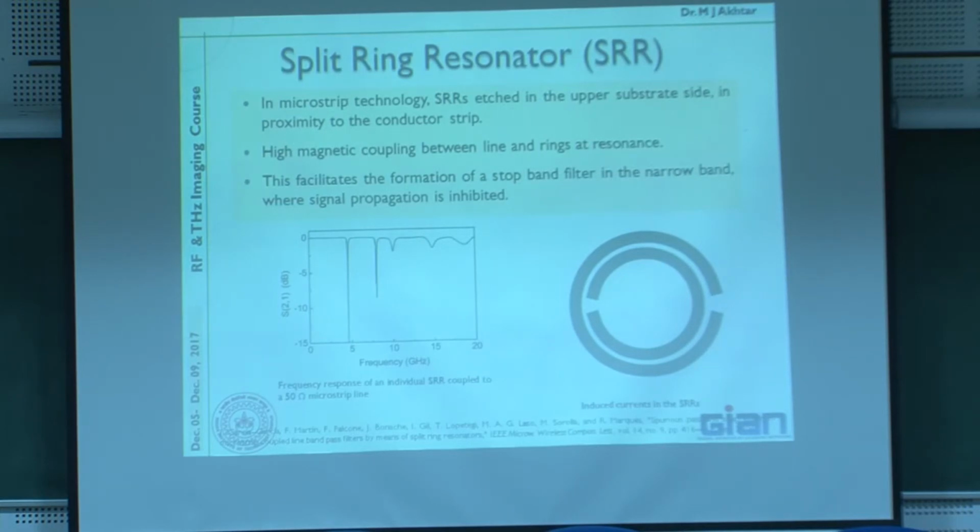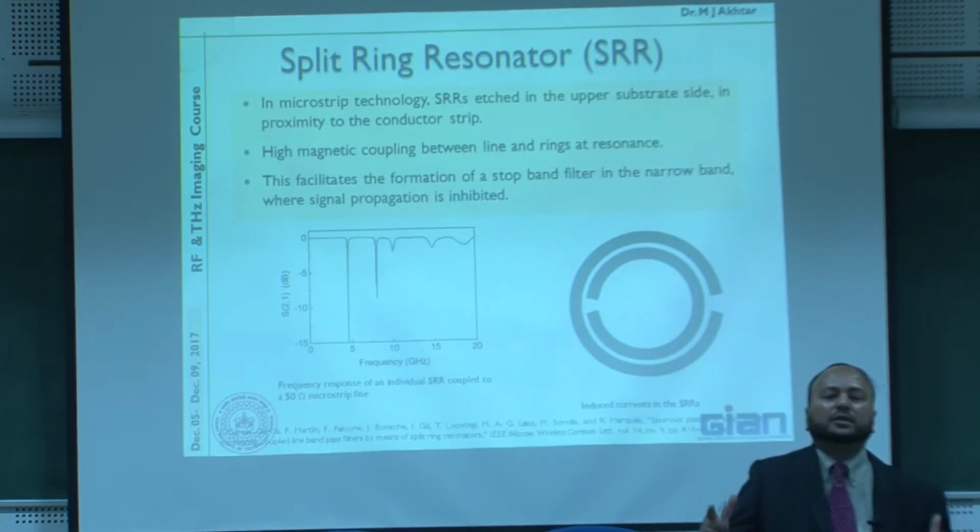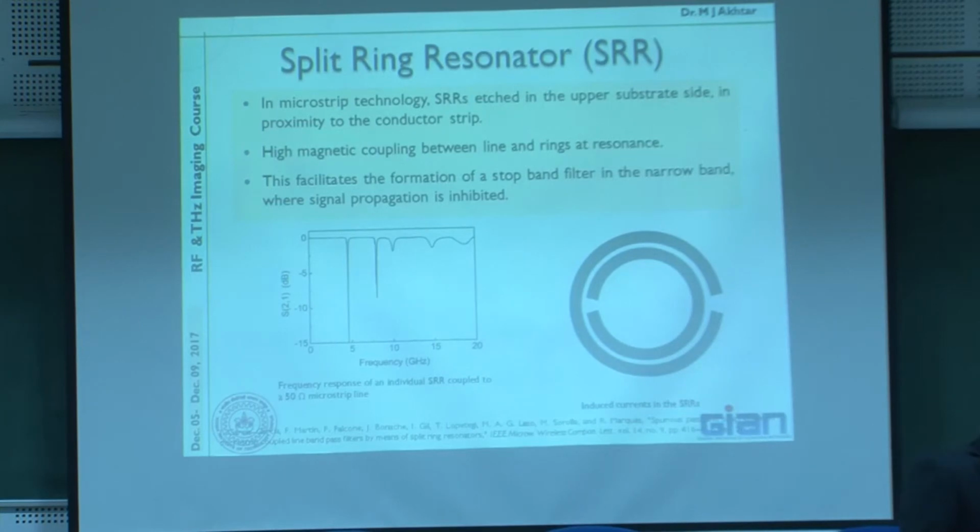So basically, if you design them and find this property, they show resonance at some frequency. For example, this shows two frequencies, one here and one here. Now if you recall, the whole idea of resonator based sensing was starting from a waveguide: we designed a waveguide based cavity, found the resonant frequency and quality factor, and now we are saying we have designed an SRR, a split ring resonator, and we have obtained what we call the resonance, because at one frequency it shows a dip like resonance characteristic.